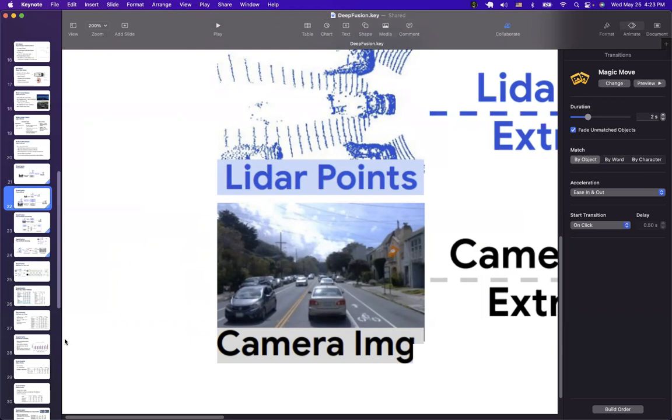We can only get the depth, how far away an object is, via LiDAR, this kind of sensor, right? So by combining them, we create the RGB image with depth. This is more like early fusion, fusing the raw data together to create an RGB image with depth. So this is another way of fusing these two kinds of data together, right?